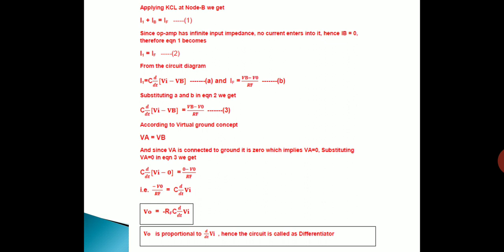Similarly, the current IF is the current through the resistor, and we know that current through the resistor is V by R. So what is V here? Voltage across RF. What is the voltage across RF? The potential difference between the two ends. One end is connected to VB, another is connected to V0. So the potential difference is VB minus V0. Hence the current IF is given by VB minus V0 by RF. We can call that equation B.